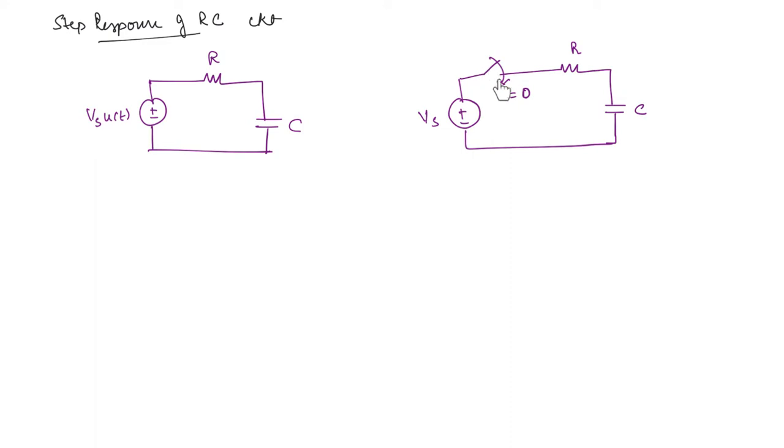Now, the minute the switch is closed, let us say a current I is flowing and this I will have a transient part. Okay. So this is the current I. Now, initial values are important. Okay. For a capacitor, we will need the initial voltage value across it. So let the initial capacitor voltage be V naught. Okay. So that means we can take this as Vc of t.